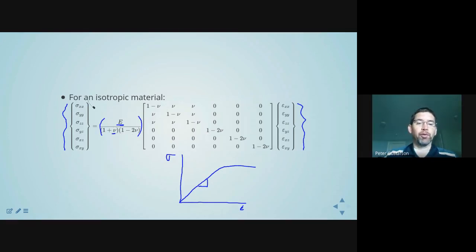So in many circumstances, when we're talking about the relationship between stress and strain and we're doing hand calculations, largely that's going to be limited to the linear elastic regime where the moduli, that's Young's modulus or shear modulus and Poisson's ratio, is likely sufficient. And then you're calculating how much stress occurs and basically evaluating whether it stays under yield or exceeds yield before you continue to do more advanced calculations if you need to.